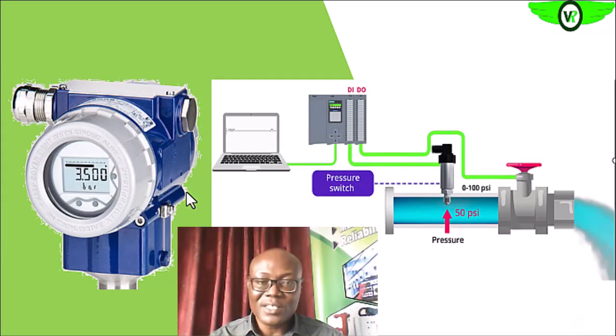So here is a complete configuration of the process: the pressure sensor here, the transmitter that sends the signal to your controller, then your controller to your final control element, which is the valve.